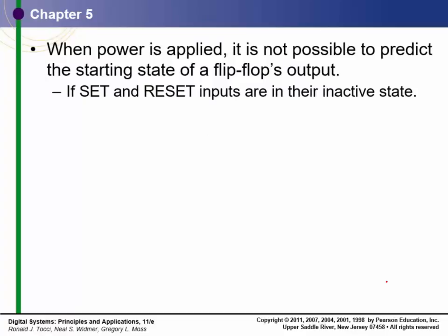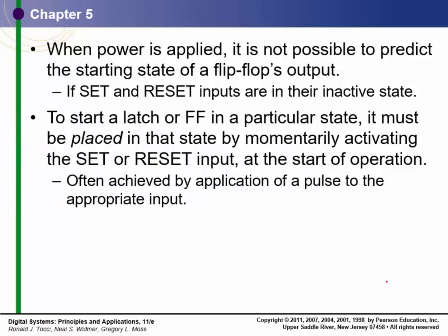So again, when powered up, and this is true for all flip-flops, you don't know their state. Normally, if you have a circuit with flip-flops, you will have a power-on reset circuit that will reset them to a known state. So if set and reset inputs are in their active state, to start, it must be placed in a state by momentarily activating it to start operation.